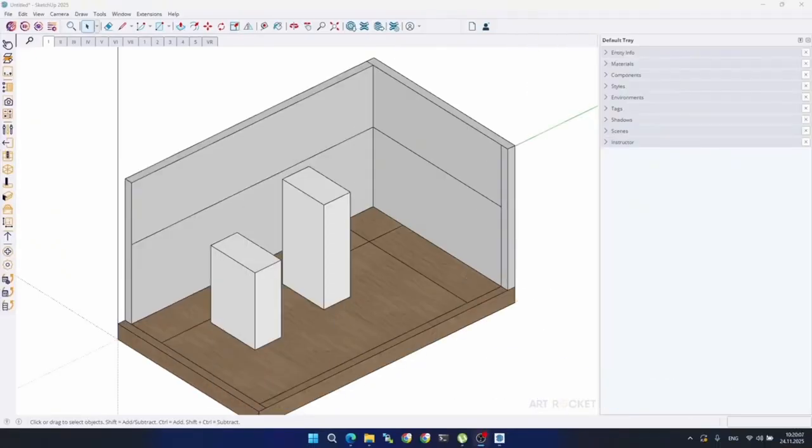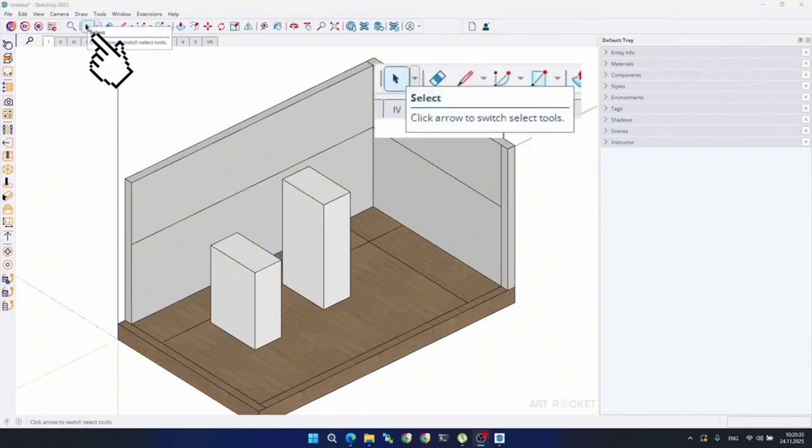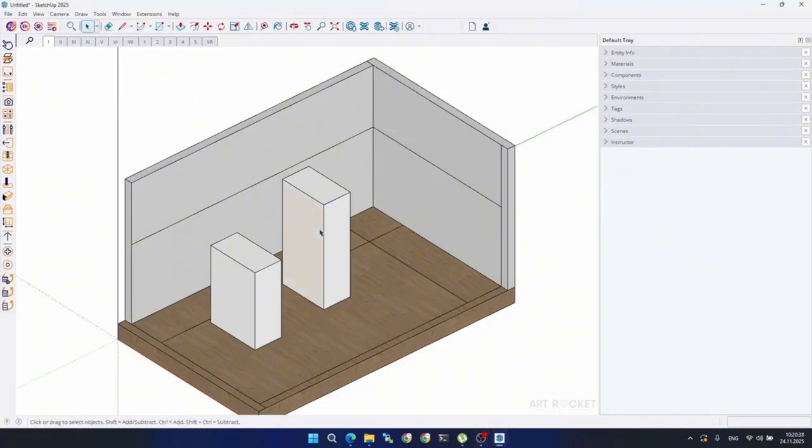After a shape has been drawn and transformed into a volume, it's useful to organize it as a group so it doesn't stick to other geometry in the scene. A simple object is visible in the scene, for example, a block created using push. Using the Select tool from the left toolbar, a click is made on the object's surface, then a quick triple click is performed on the same geometry. 1, 2, 3. This selects all connected faces and edges of the object. You can see that the entire volume is highlighted in orange or shown with an outlined contour, indicating full selection.